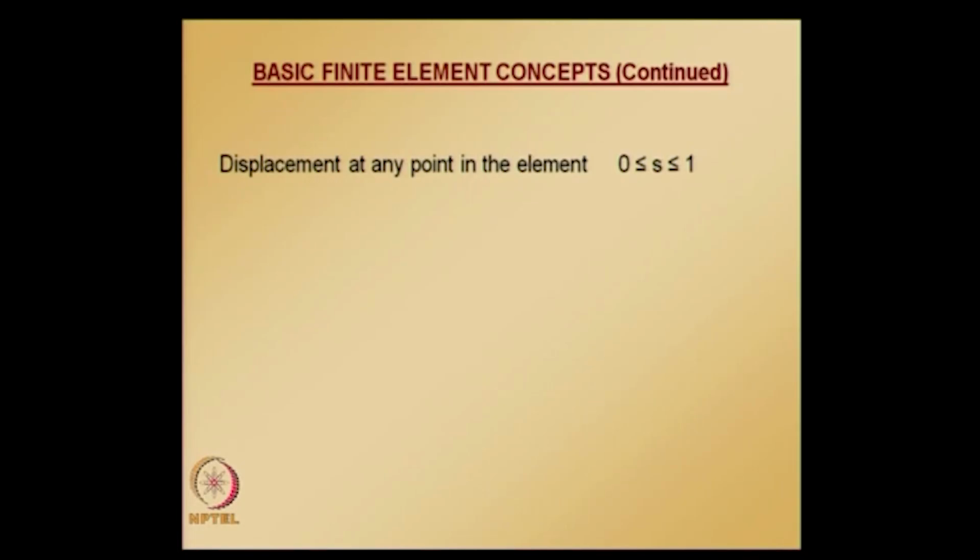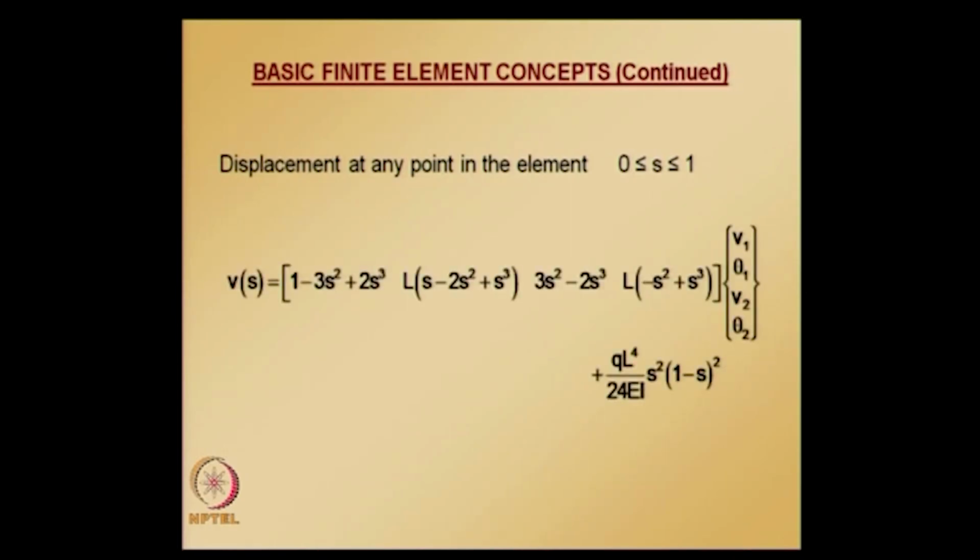When you are calculating moments and shears, you add the fixed end solution to the moment and shear that you get from finite elements. So for displacement, the nodal values that you get from the finite element method are exact, but at any point in between we need to add the fixed end solution. The second term shown is the correction factor, which comes from the fixed end solution.